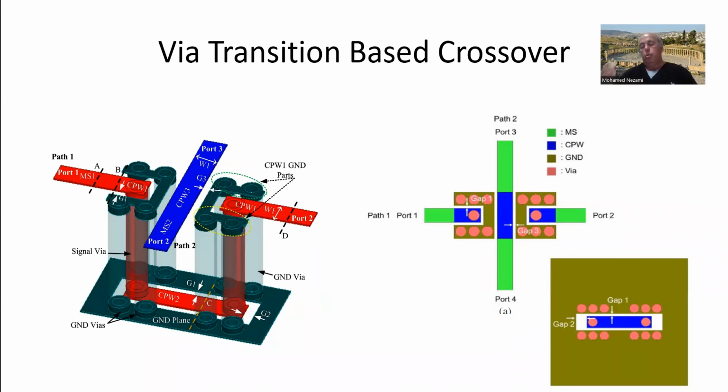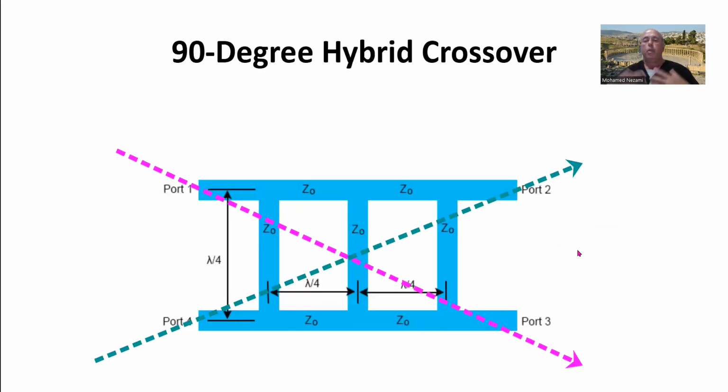Okay, in fact, they have a name for it. It's a quasi-coaxial connector in PCB, which means you design a via and a certain pattern of ground vias around it to mimic a coaxial line. And you could set that up so that the inner diameter of the board material surrounding, bounded by the ground vias, and the diameter of the via itself, you could design it such that you can actually preserve and implement a 50 ohm.